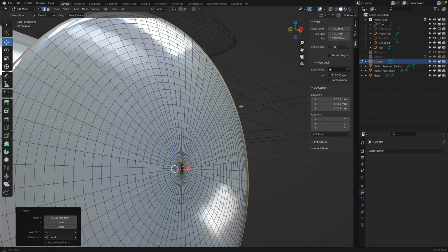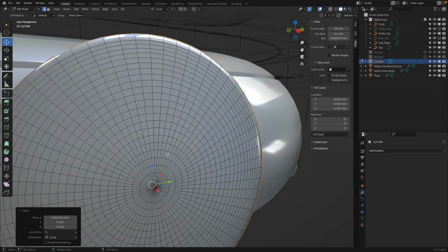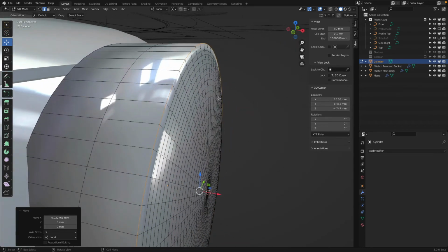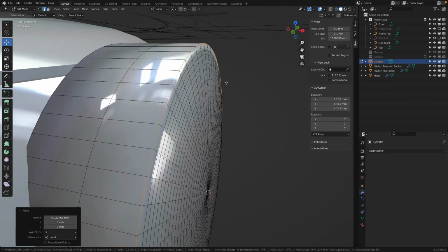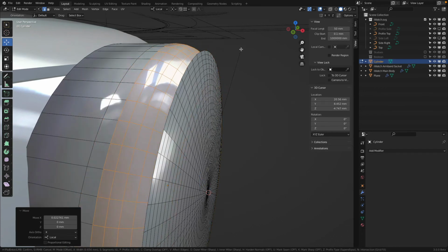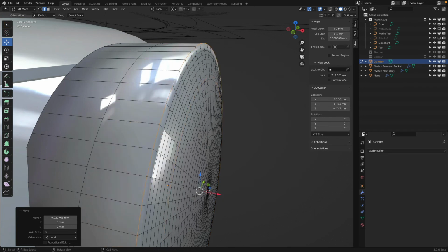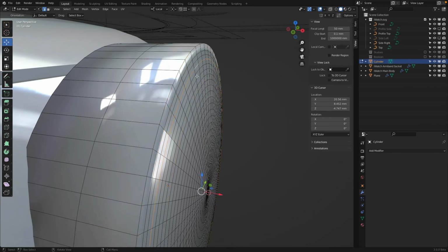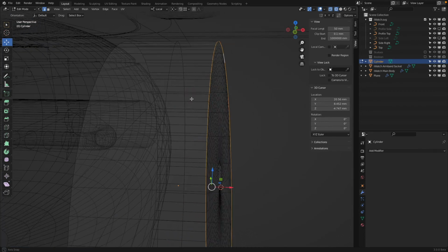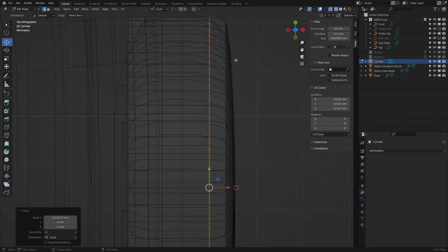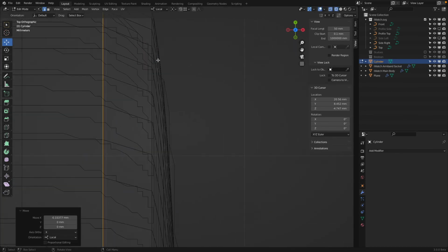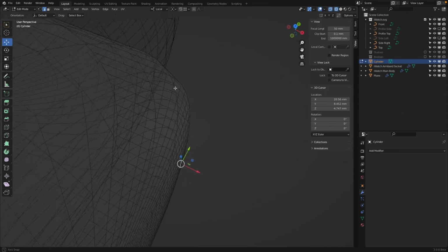So we have actually, as you see, a nice front part. Then we have this is flat, and now we can fillet this. And we run into issues. What's going on here? Well, because this fillet will start cutting into these lines, so that doesn't work. How do we fix this? Easy. We know the tools. So this edge we can bring back to here.